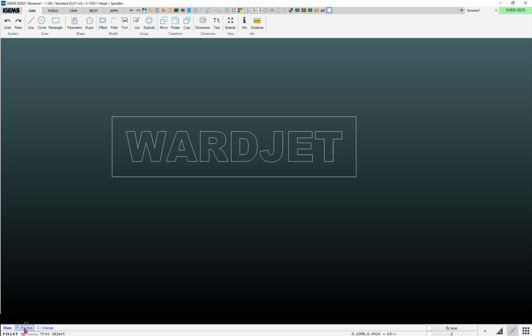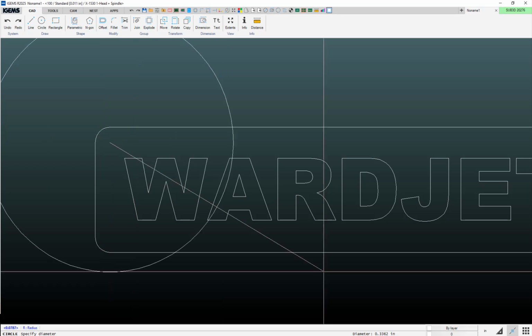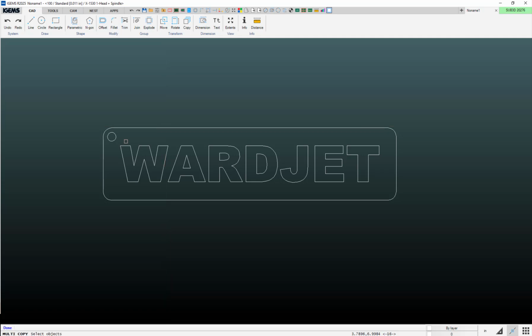And then I'll do the P polyline option. When I click on that, then all 4 corners will quickly be radii-ed, if that's a word. And we might as well put a couple circles on here for some bolts or whatever. Let's see, diameter, we'll go with 0.25. We'll do our copy command, or we could do mirror or whatever. From center of here, center of there, that should suffice.